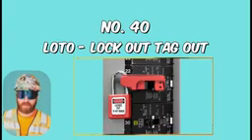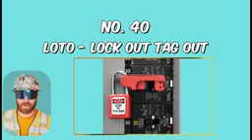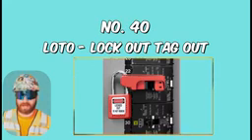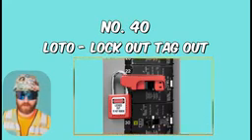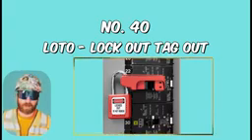LOTO, lockout, tagout. Lockout, tagout is when an electrician is working or providing a service, they place a lock on the breaker at the panel so someone doesn't flip it on accidentally while they're trying to complete their work. It's used as a safety precaution.